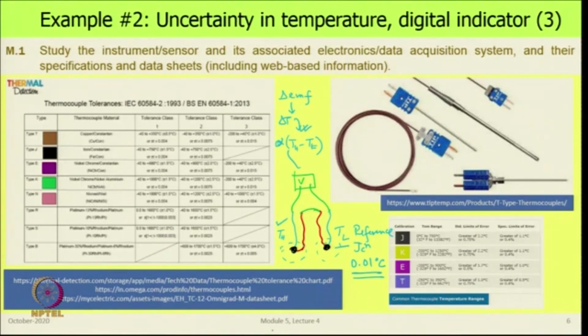That is how the thermocouple works, but the signals are very low, so we send it to an amplifier and then digitize it and do this reverse calculation: convert the EMF into a delta T, we need a calibration there, and then add the reference junction temperature to it, and we get the temperature that we are trying to measure. So, when we are measuring, it is this part here which we will take and locate where we want to make the measurement.